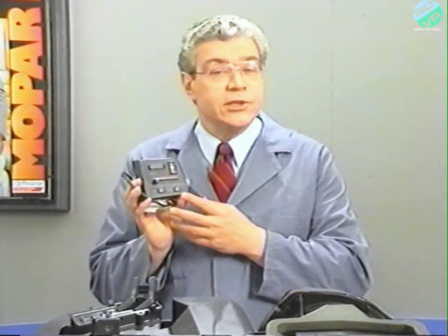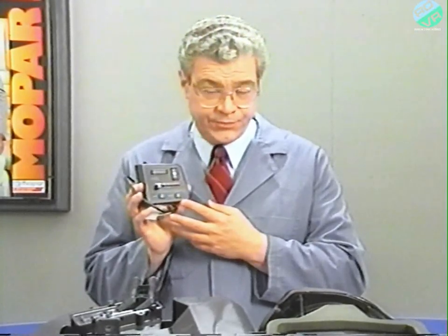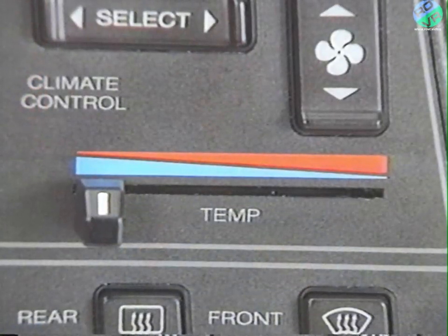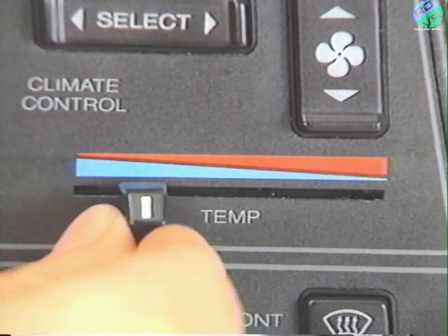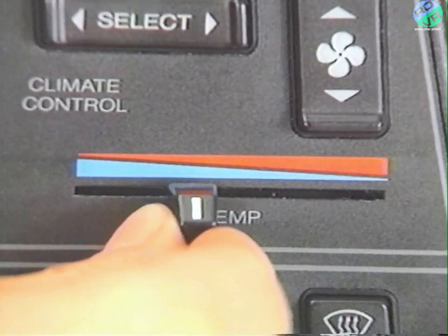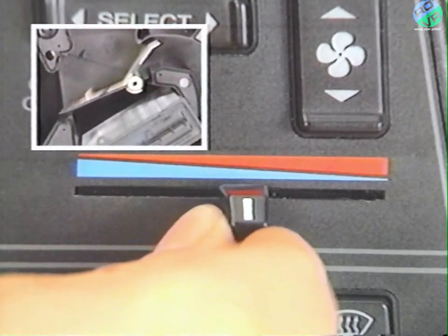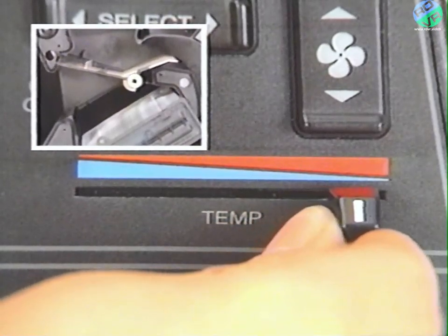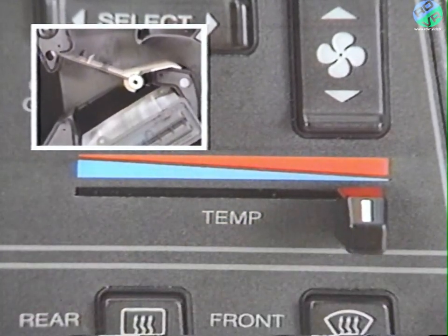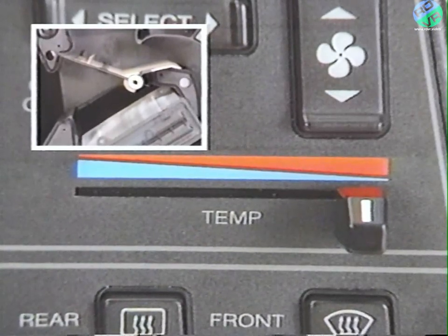Keep in mind that we've been covering the climate control system as it occurs on a vehicle equipped with AC. The heater-only system does not use the temperature sensors. Instead, the ACM on heater-only systems uses the position of the temperature select lever in controlling the position of the air mix door. There is a direct relationship between the position of the lever and temperature control. As a result, temperature control on the heater-only system operates in the same way as an electrically controlled manual system.